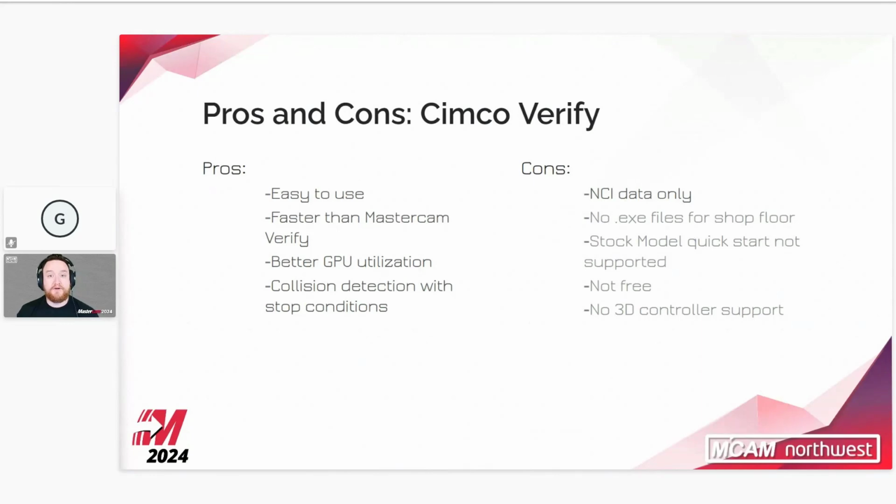Now, if you don't have a GPU, this will actually cause a major problem. Some people don't have a GPU in their system and they run Mastercam. It's not technically supported, but a lot of people do it anyways, usually to fairly poor results, but working results nonetheless. If you don't have a GPU, Cimco Verify simply isn't going to run because of some of the requirements that it has. This also caused Tim a problem because he's running Parallels and it doesn't have the correct OpenCL rating, I think. So that caused a bit of a problem.